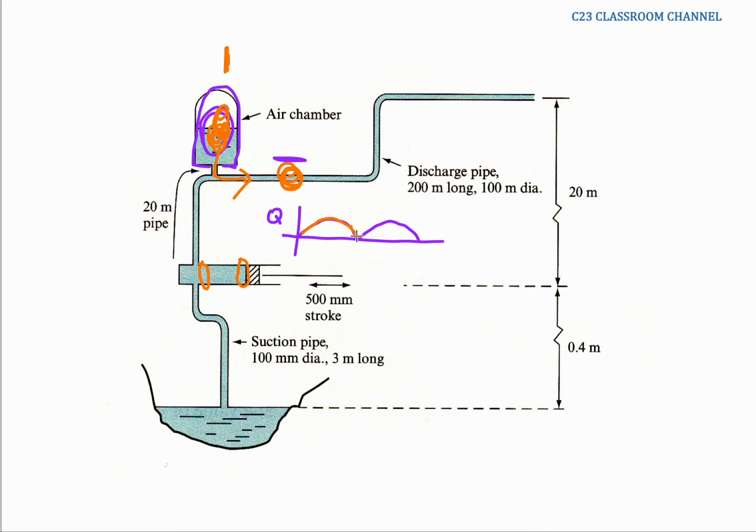In the tutorial later on, we will see that the calculation of losses with and without an air vessel is totally different. The losses for a pipe with an air vessel are relatively small compared to the friction for a pipe that has no air vessel.